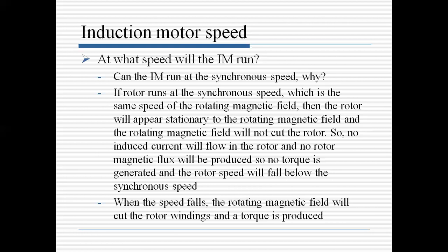The rotor rotates because the stator flux cuts the rotor windings and an EMF is induced in the rotor windings. If the rotor also rotates at the constant synchronous speed, it will appear stationary. So no EMF will be induced in the rotor, and no rotor magnetic flux will be produced.